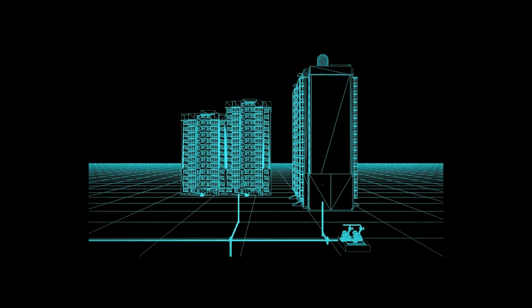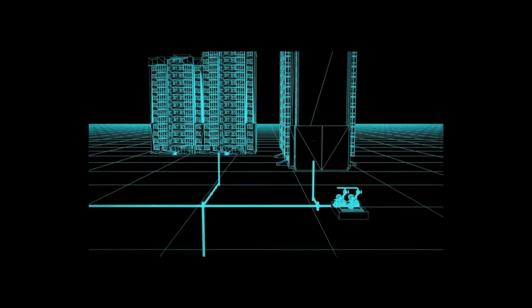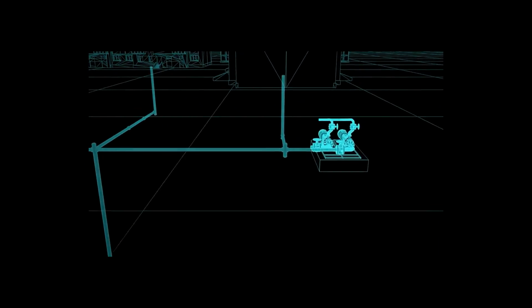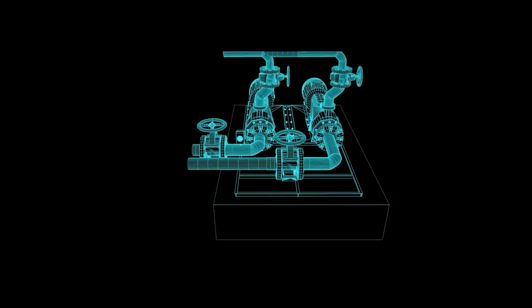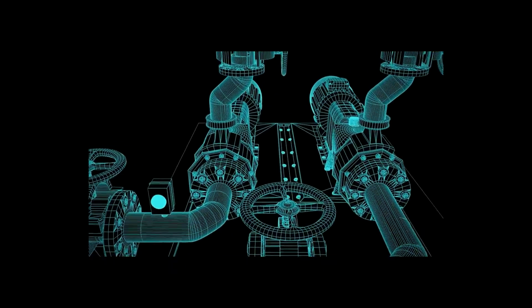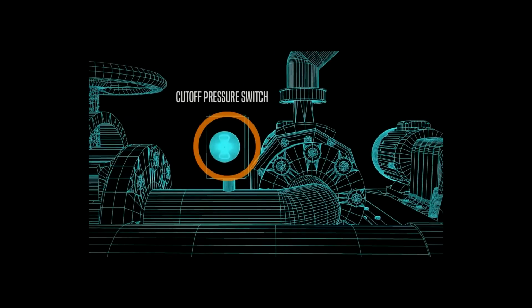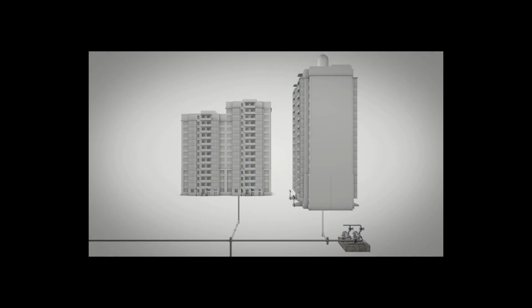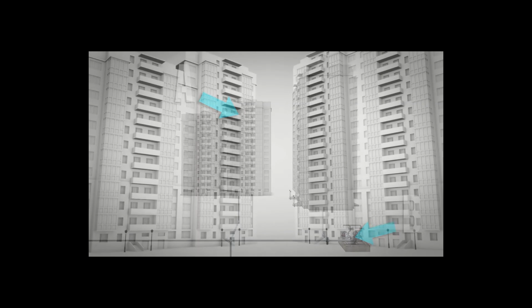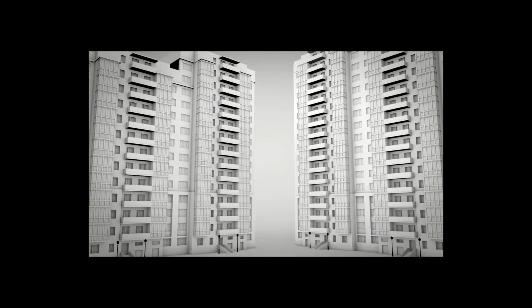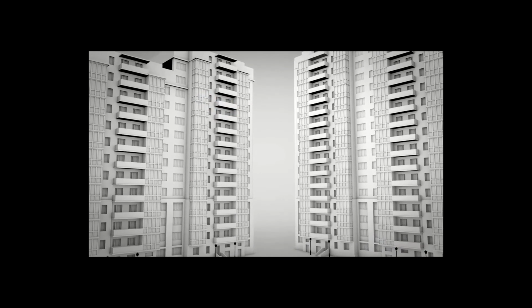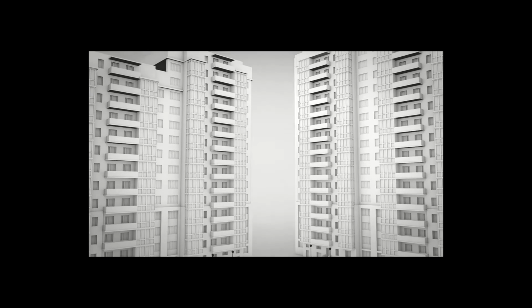Backflow could be more likely if the pump on the building on the right does not have a cutoff pressure switch for when pressure drops, or when the booster pump stops running. This back siphonage could be made worse because of the height of the building on the left. Point A would be the first to experience negative pressure and potential backflow. High elevation differences can greatly magnify the effects of low pressure, increasing chances for back siphonage.